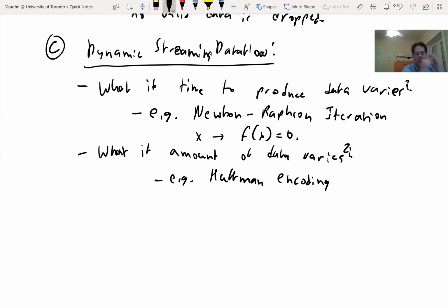By doing that, it compresses things, so it cuts your file sizes or cuts your bandwidth in a communication system, so it's good. But it fundamentally is using a different number of bits; its output bits vary depending on what you sent it. That is how Huffman encoding works: short symbol patterns for common symbols and long symbol patterns for uncommon symbols. So it's fundamental that it's going to vary.